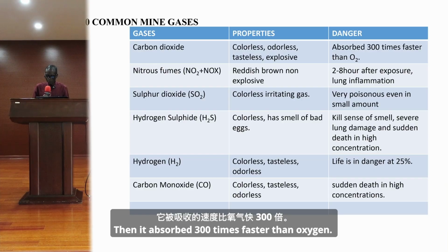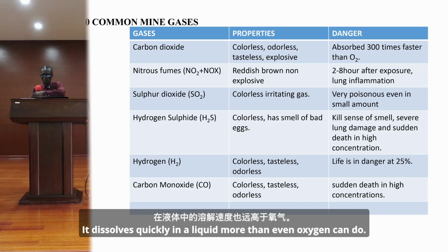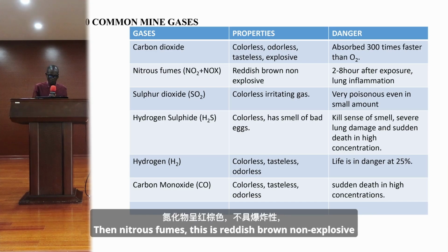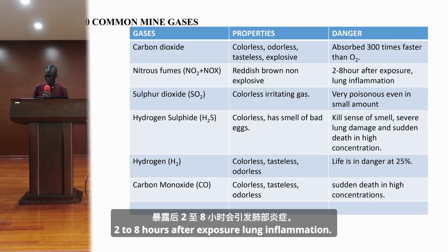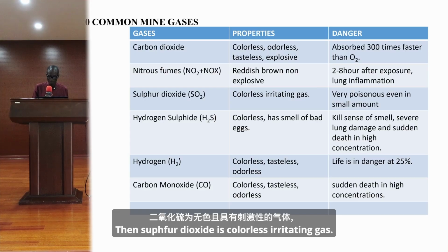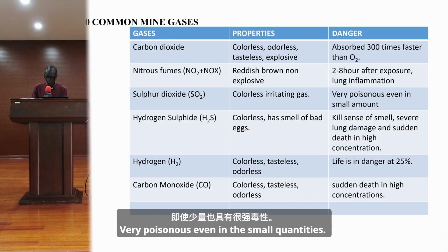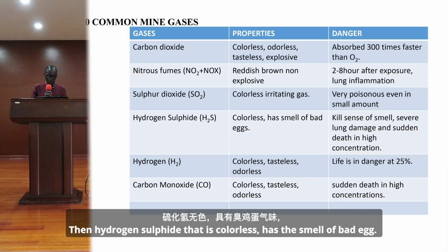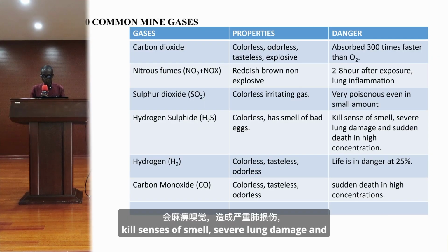Then it is absorbed 300 times faster than oxygen. It dissolves quickly in a liquid, more than even oxygen can do. Then nitrous fumes, this is reddish-brown, non-explosive. 2 to 8 hours after exposure, lung inflammation. Then sulfur dioxide is a colorless, irritating gas, very poisonous even in small quantities. Then hydrogen sulfide, that is colorless, has the smell of bad egg, kills the sense of smell, severe lung damage, and